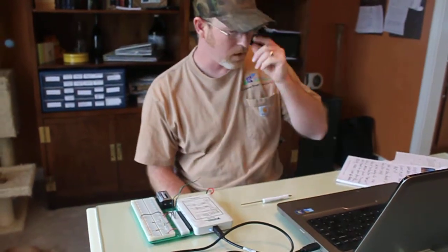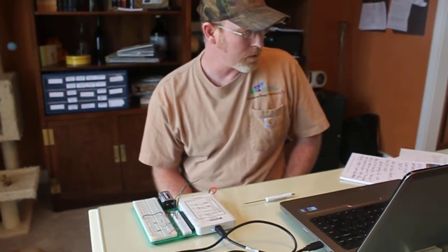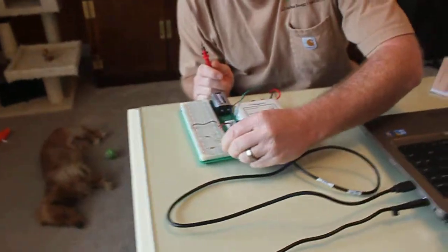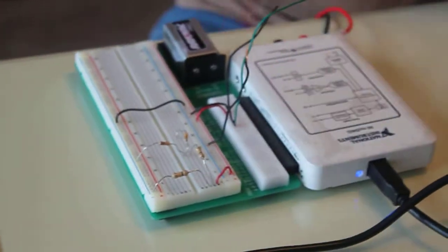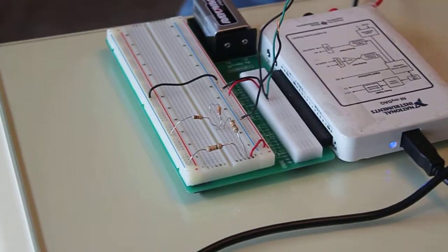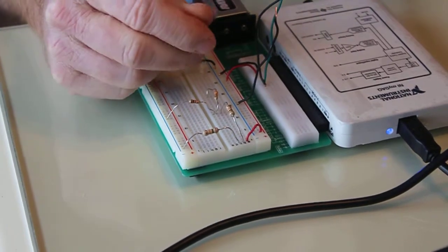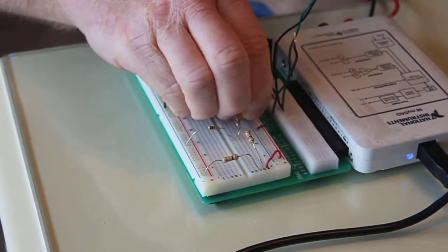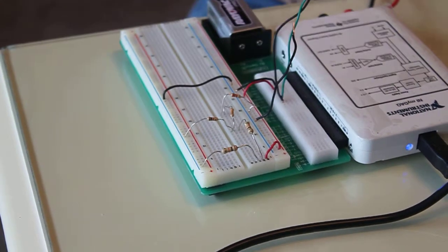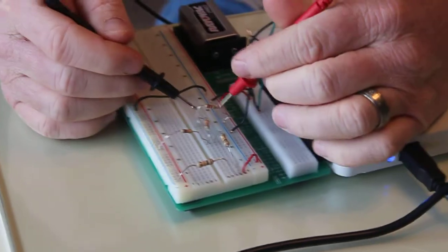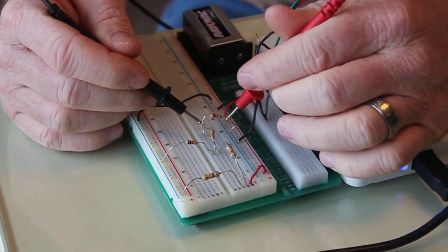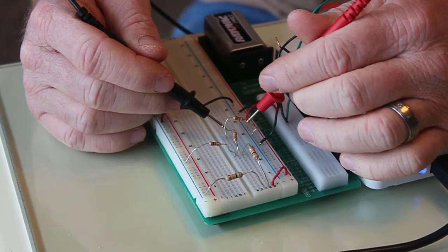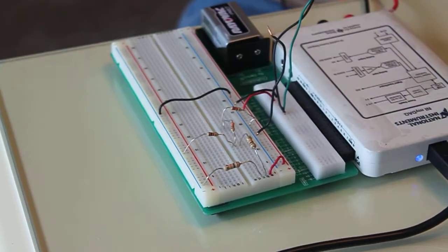Once you get those measured, next thing you're going to do is supply power back to the circuit as before with the 5 volts, and we're going to place each one of the new load resistors into the circuit. As so. And then we're going to measure current, and we're also going to measure voltage across these. Actually, your voltage is already given by your Thevenin equivalent voltage, so really all you're concerned about is your current through these.